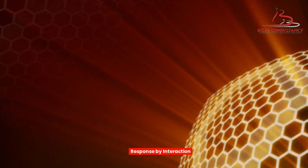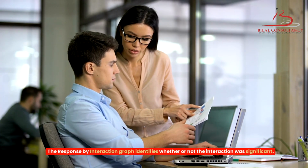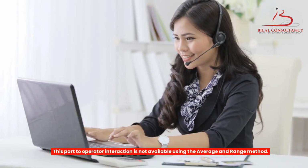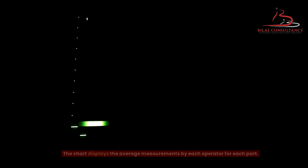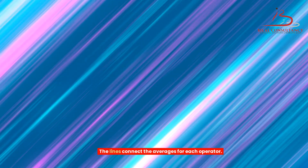Response by interaction. The response by interaction graph identifies whether or not the interaction was significant. This part-to-operator interaction is not available using the average and range method. The chart displays the average measurements by each operator for each part. The lines connect the averages for each operator.